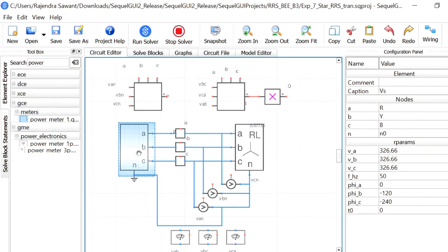We can find the phase voltage here because we know 400 volt as the line voltage given to us, which is the same in all the lines. This 400 volt can be converted into phase voltage, and the phase voltage is found to be 400 by root 3.